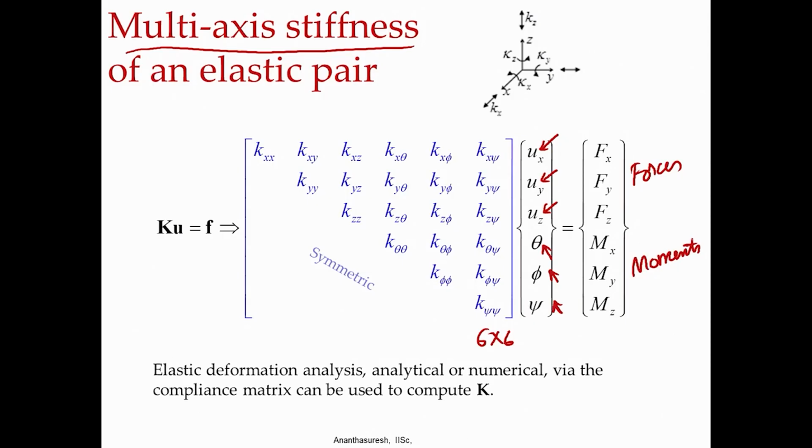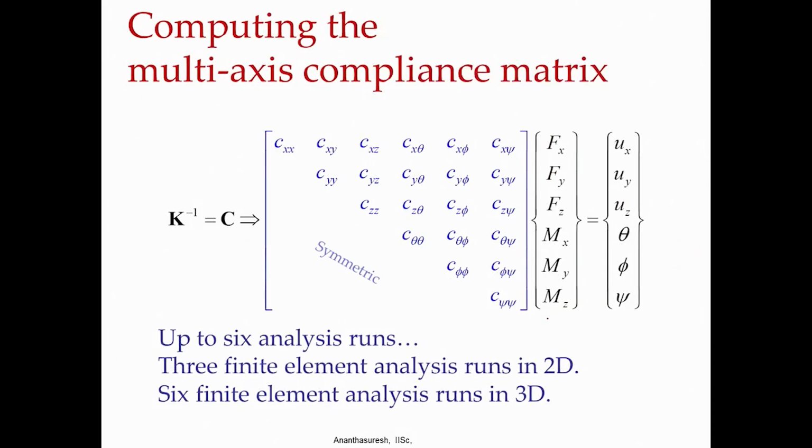All these things differ, as we had noted in the first lecture itself. How these values, cross values, diagonal values, how do they differ? Okay. How do you construct this stiffness matrix, or its inverse, the compliance matrix? How do you do that? To do this, we have to do 6 finite element analysis runs. Today we have finite element, you do not have to go for all these approximate formulae, because they are approximate, but they are useful in design, let us not forget that.